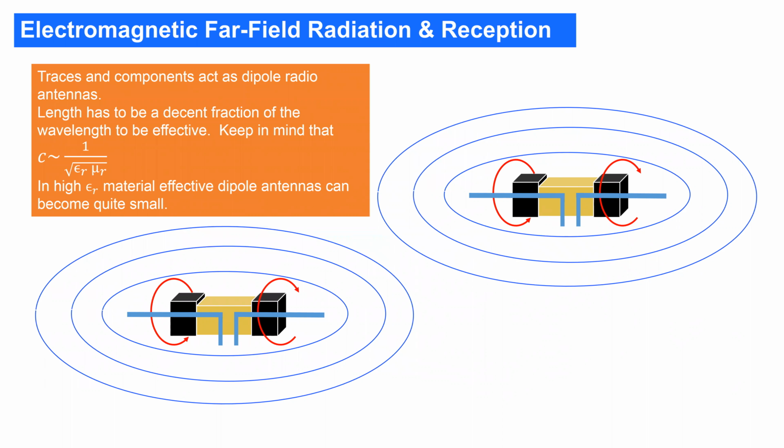Typically for a DC to DC converter, the energy falls off in the 700 megahertz range, so you won't have any energy above a gigahertz, and for gigahertz, the wavelength would be 30 centimeters in free air, so normally you don't have such large components. But if you have wires or larger areas, PC boards also, you will sometimes see that you emit electromagnetic waves directly.